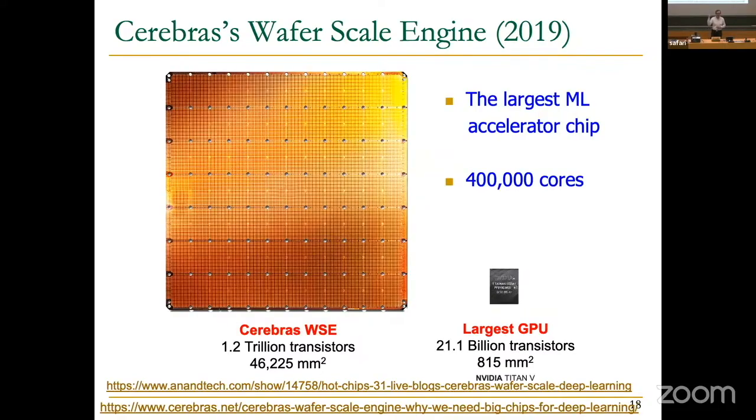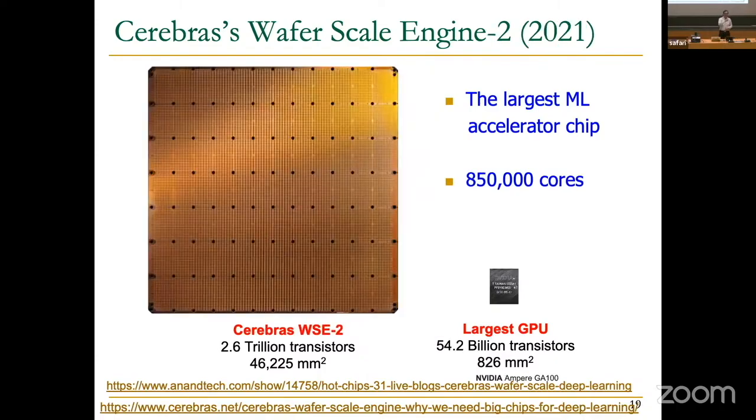I will show you that at the core of it, this has many processors inside. Well, this is the newer version, if you will. This has many processors inside, and each processor is a SIMD processor internally, and they communicate with each other. So it actually consists of multiple paradigms. It's a multiprocessor of SIMD processors or vector processors, if you will. And this is designed as a wafer scale chip, and there are lots of units over here, according to Cerebras, 850,000 cores.